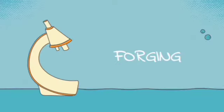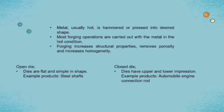Next is forging. For forging, metal, usually hot, is hammered or pressed into the desired shape. Most forging operations are carried out with the metal in the hot condition. Forging improves structural properties, removes porosity, and increases homogeneity. We have two types of forging. The first one is open die. Dies are flat and simple in shape. An example product is a steel shaft. The second one is closed die. Dies have upper and lower impressions. For example, the product is an automobile engine connecting rod.